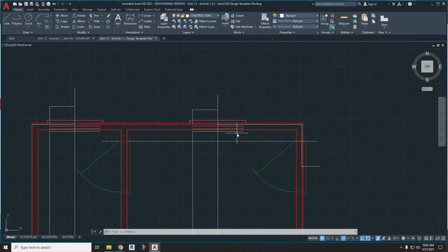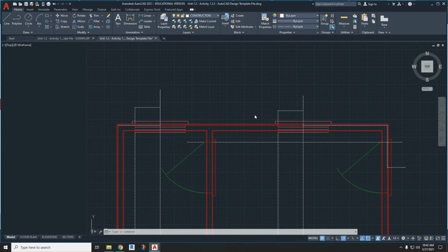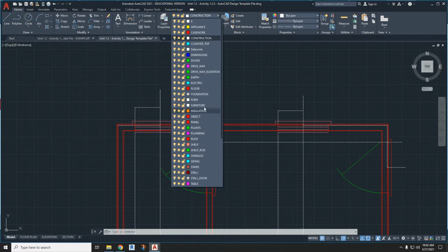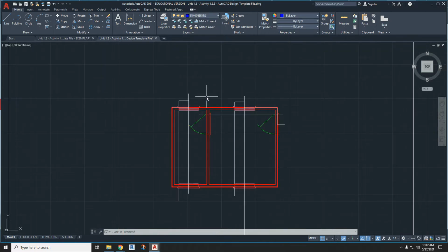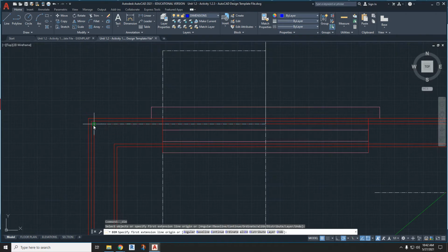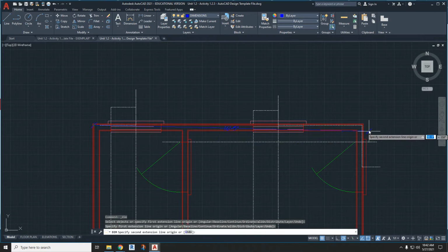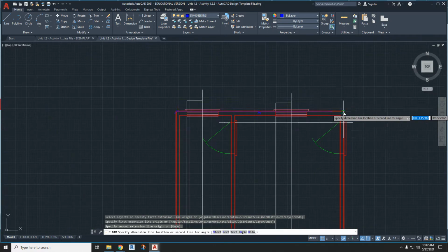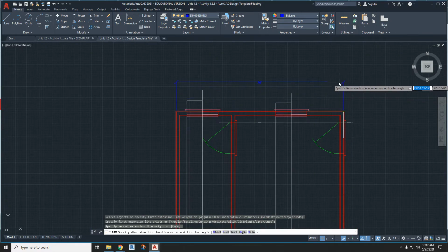Before we get rid of any construction lines, we're going to use some of them for dimensioning purposes. So let's switch over to the dimension layer. And the way dimensions work is you have 3 layers of dimensions. The outermost are the biggest dimensions. So hit this dimension tool. What I mean by outermost is from the outside edge of the stud to the outside edge of the stud. That's the outermost dimension, the biggest dimension. So that's the overall wall length.